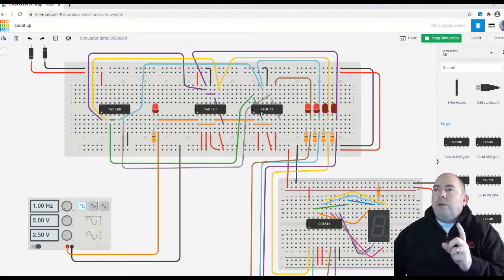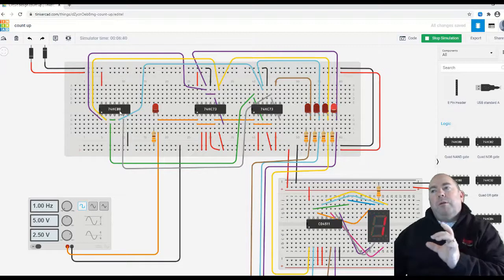The way that we handle the third one, we are going to determine J and K on the third one. That is going to be an AND function, which is basically the result of this purple and yellow wire here, which are output 2 and output 1. So if flip-flop 1 is a 1 and flip-flop 2 is a 1, that will produce a 1 as our result here. So if we have a 1 and a 1 in our first and second bits, at the time when we clock it, then we will put the third bit in toggle mode.